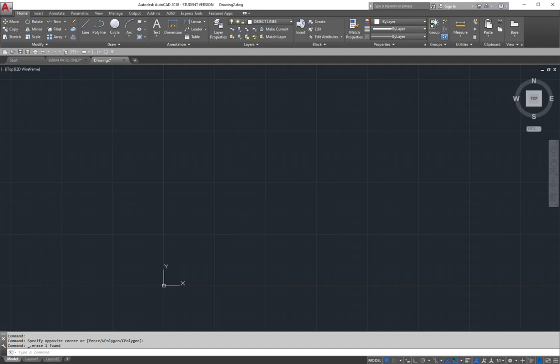B12-4A is the first one. You have the front and the top view, and then you need to add the missing right side view. The same thing happens with B12-4B and 4C. It's going to be just the front and the top view. As you see them on the handout, that's exactly what you're going to recreate.